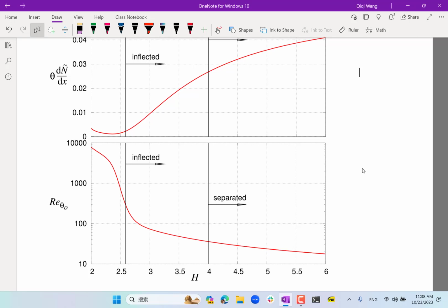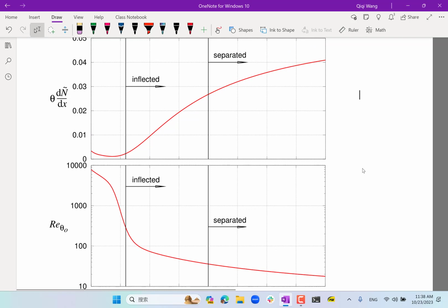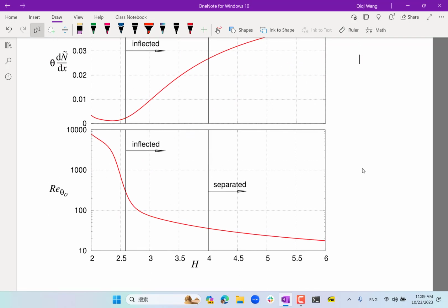They can be in a very quiet flow. It can be like 10 to the -7, 10 to the -8, compared to the free stream velocities. Really, really tiny perturbations. So people who are trying to maintain laminar flow are very, very careful. Even if a bug sticks to the leading edge, there is no way you're going to get the same laminar flow you got before, just because of the small perturbations introduced by the bug or a spray of salt water or something like that. Okay, so this picture basically shows you the two most important things that affect transition.